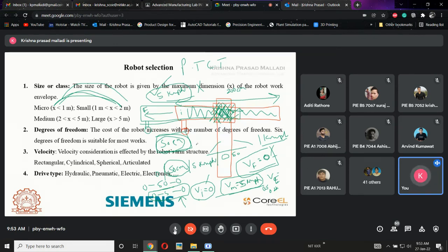That is why, based upon the end application, we define what type of velocity the robot needs to maintain. If I'm using a 50 kg payload robot, the robot doesn't need 5 kmph. Why? Because it is itself picking some 100 kg or 50 kg of load. So it should have limited, low speed to reach the final destination or to maintain precision or accuracy. So based upon that, we define how much velocity is the maximum needed for that robot. We need to define that based upon these two things. Again, these two are interdependent.